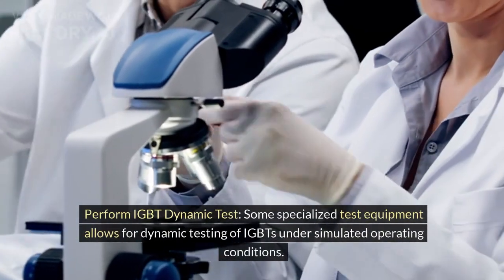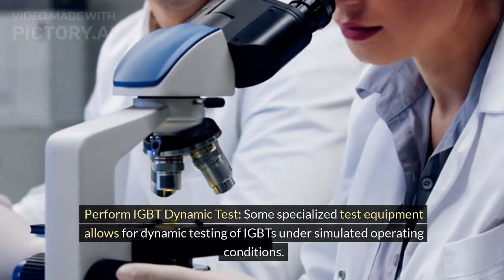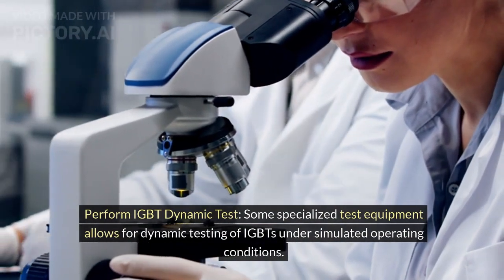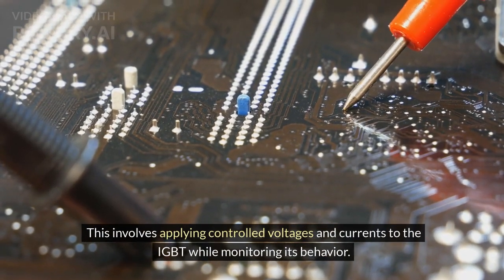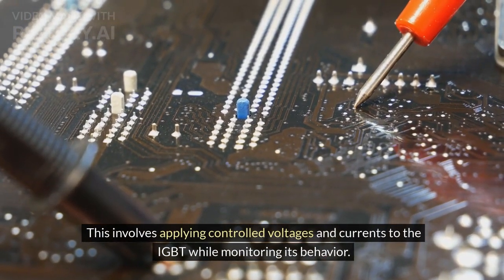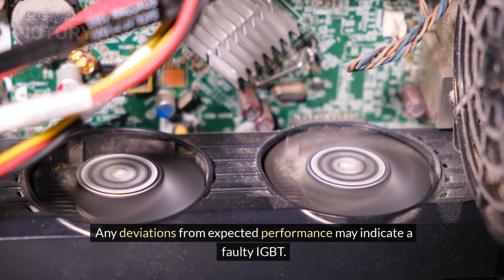Perform IGBT dynamic test. Some specialized test equipment allows for dynamic testing of IGBTs under simulated operating conditions. This involves applying controlled voltages and currents to the IGBT while monitoring its behavior. Any deviations from expected performance may indicate a faulty IGBT.